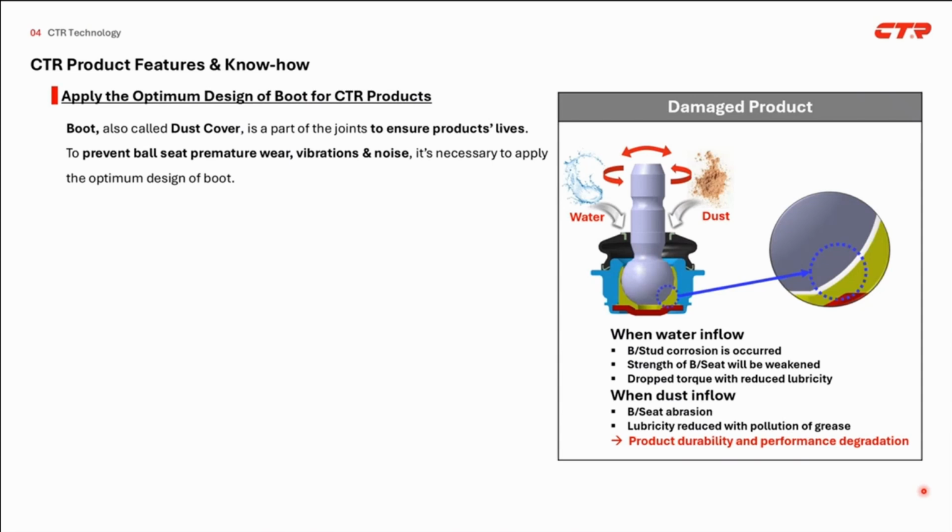Just as with water inflow, dust like soil or debris inflow will also cause wear on the ball stud. And owing to grease contamination, lubrication will be compromised. If we don't consider this movement, the boot can be negatively affected, which can lead to ball stud premature wear, vibration, and noise.